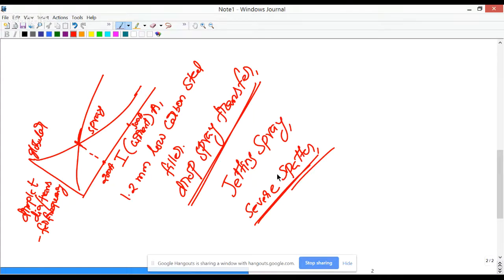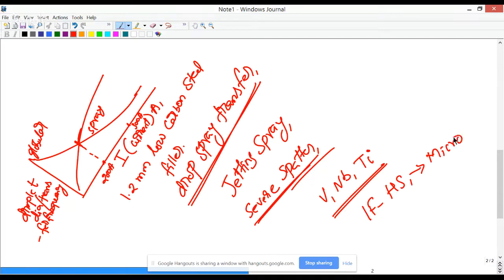Both are the same, right? By adding microalloying elements. What are the microalloying elements commonly added in steel? They are vanadium, niobium, and titanium. These are all carbide and carbonitride forming elements, so they form precipitates. So precipitation hardening is the most commonly used strengthening mechanism for interstitial free steels to increase the strength level. Recall my lectures, the interstitial free high strength steel is actually microalloyed. So the vanadium, niobium, titanium form vanadium carbonitrides, vanadium carbides, or the mixture of vanadium, niobium, and titanium carbonitrides.